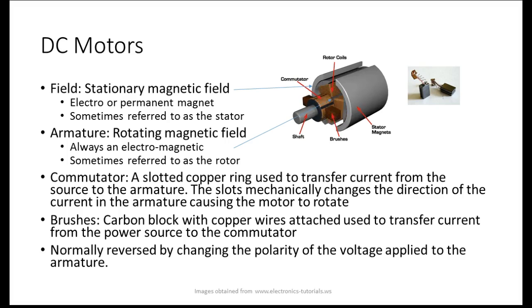And there's several reasons why, because with shunt motors and separately excited motors and compound motors, if the field opens when the motor's running, the motor can run away. If the field to the armature opens, the motor will stop. So it's safer to do it with the armature, even though a series motor won't make any difference because you can't open up the field without opening up the armature. But what we need to understand is that we come up with a standard way. If we've got a standard way, we always reverse DC motors the same way, by reversing the what? Armature.